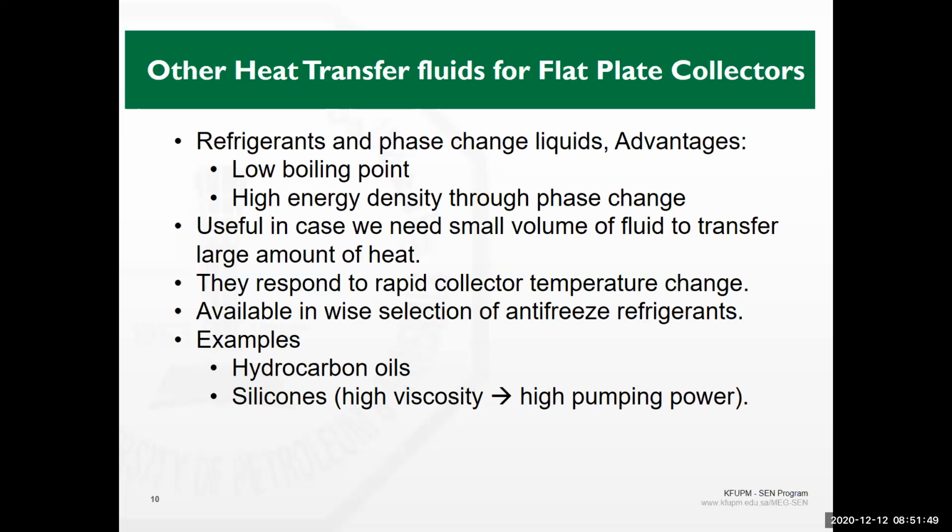And then after sunset, what would happen? No further energy added to the unit. So the wax starts to cool down. Cooling down, it means it transfers its energy to the air which is passing on top of the plate. And then it starts to solidify. As it solidifies, it is releasing its latent heat of fusion. And accordingly, additional energy is being transferred to the air. So you can keep your air heating maybe a couple of hours after sunset by just having the storage in this unit.